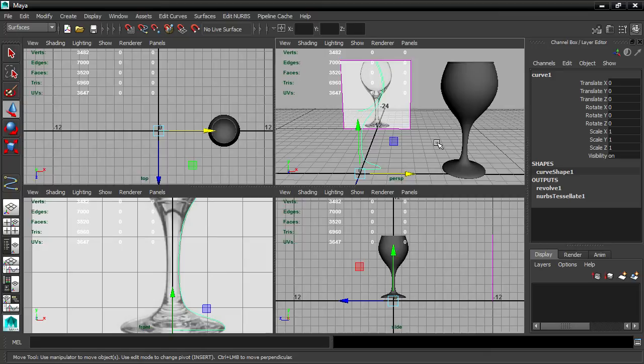This especially happens if you have a lot of commands, like if you're doing polygon modeling and you issue 400 commands, and then you have a construction history that's 400 nodes deep. It's going to calculate very slowly, and there's a very high risk that it's going to become corrupted. When you open that scene, especially in a later version of the program, those nodes may be calculated differently, and you may get a scrambled mess. So before you sign off on a project, you're going to want to delete the construction history. So let's just do that real quick.